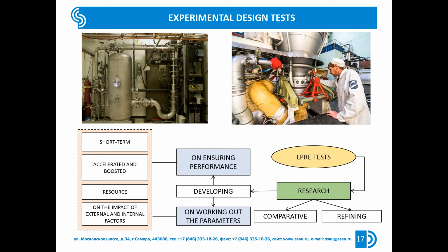In a number of cases, complex weighting of tests is conducted simultaneously on parameters, duration of operation, and number of switchings. The limit values of parameters of the weighted modes of the liquid propellant rocket engine must not exceed the values at which the physical picture of the process under study changes. In the process of developmental testing, the performance of the liquid propellant rocket engine under some emergency situations is also investigated. For certain types of liquid propellant rocket engines, such as spacecraft propulsion correction systems, accelerated abbreviated tests may be